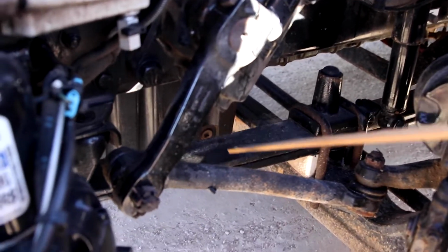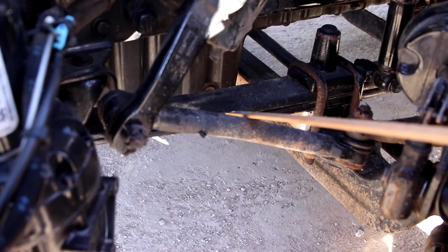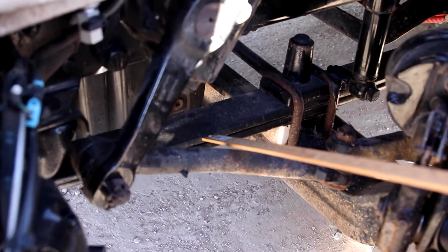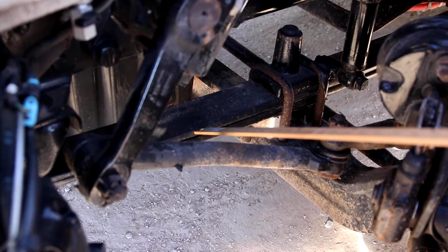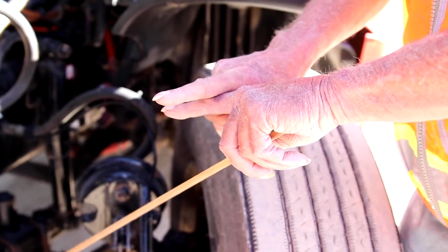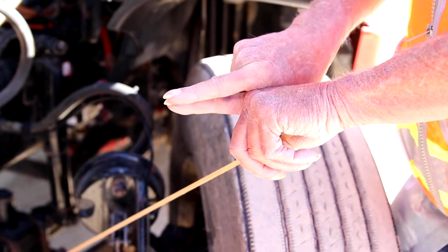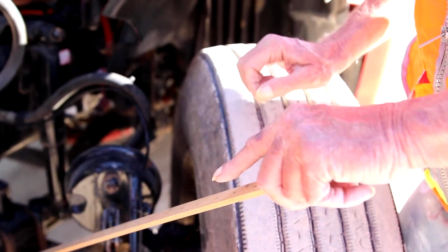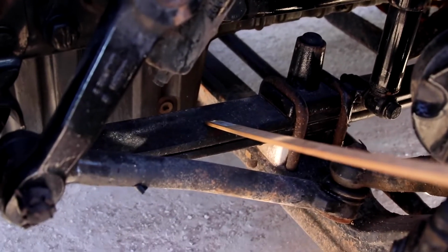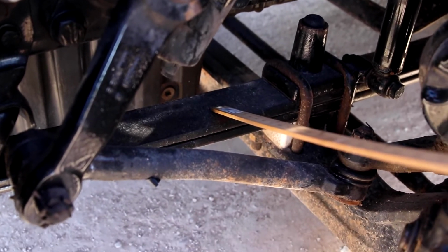These are your leaf springs. They are mounted securely to the vehicle, and what you want to do is say they're not scissoring, and that means they're doing this. They're scissoring apart or shifting. They're going from one side to the other. They're not missing, damaged, or broken. No cracks and no illegal welds.